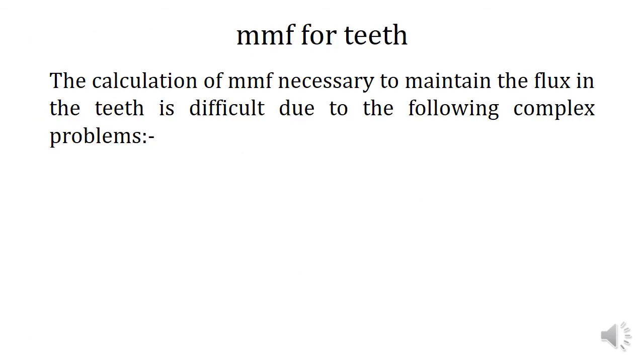Now we will discuss the calculation of MMF required for teeth. In the previous lecture, we had discussed the calculation of the MMF required for air gap. Similarly, it is very important to calculate the MMF required for teeth portion also. But the problem is the teeth is not having a uniform shape from top to bottom. That makes it difficult to calculate the MMF required for teeth.